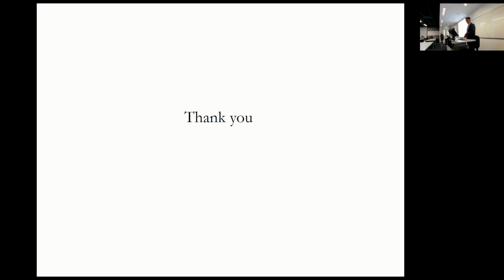I'd support the general approach to try and detail your non-structural elements to not provide stiffness to the building. So this was a little bit of an exception. However, I also support the idea of a different way of doing our elastic damping modelling. Currently a lot of our damping assumptions are, well, part of our damping we say is coming from non-structural elements.